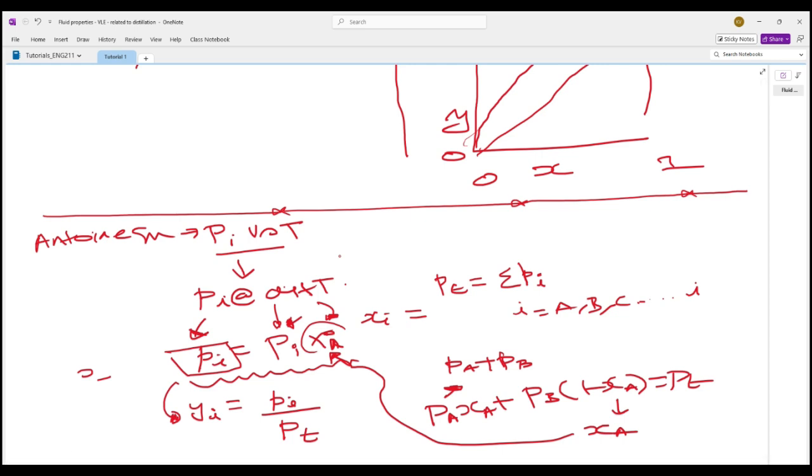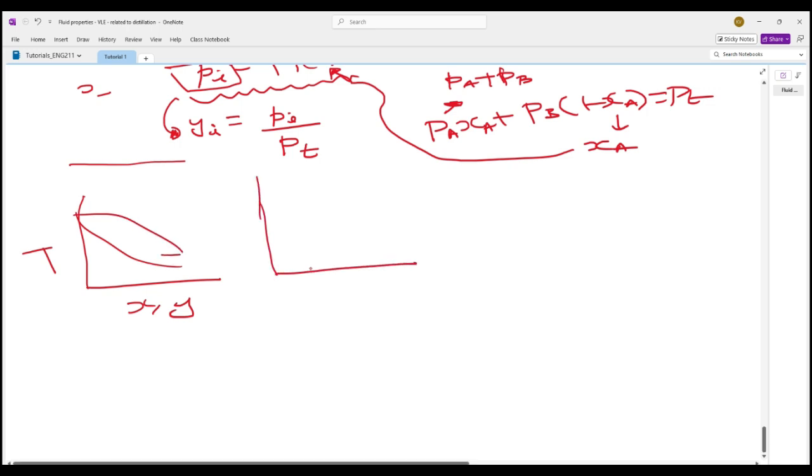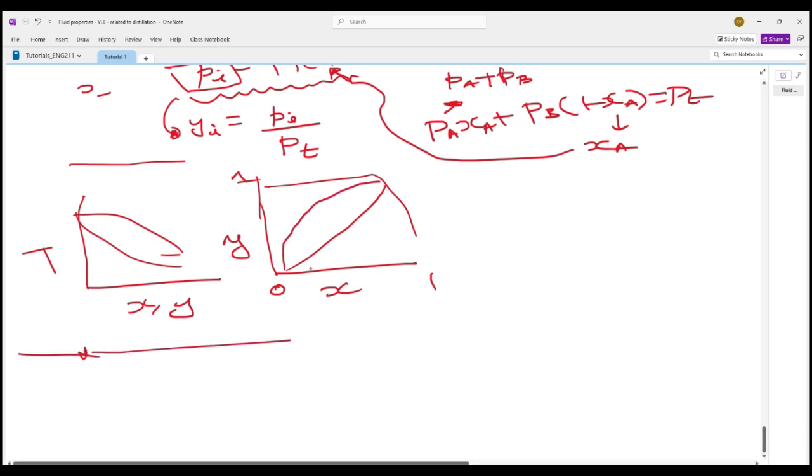And then after this we managed to translate the data into a txy diagram, where we plotted x and y on the x-axis and T on the y-axis. From there you get some curves, and we also get something called the vapor liquid equilibrium curve, typically expressed as x versus y, all in mole fraction. So some diagonal line, and that's what we learned so far.